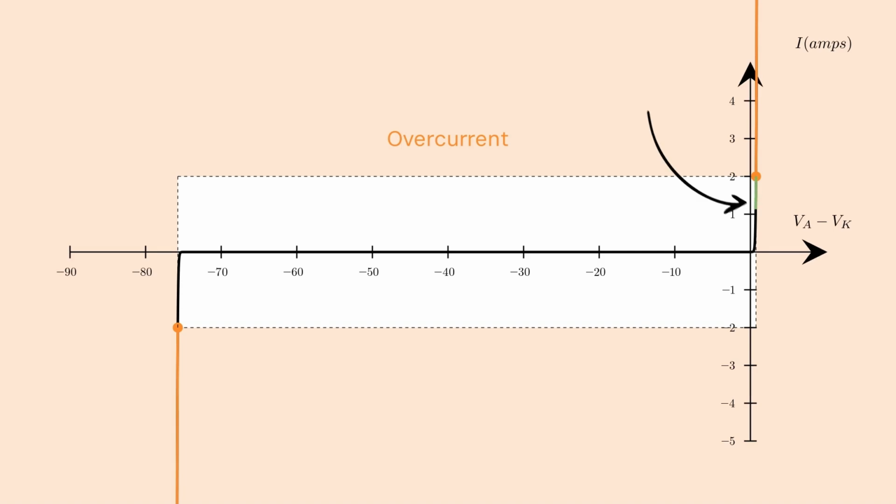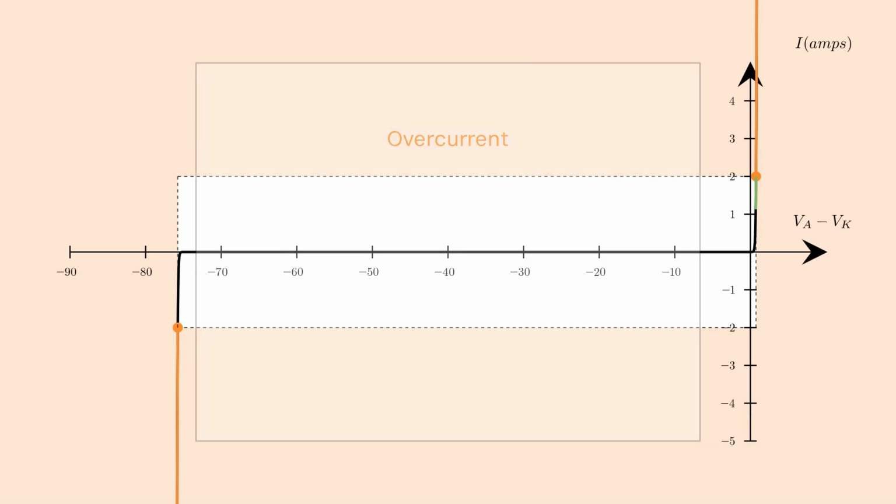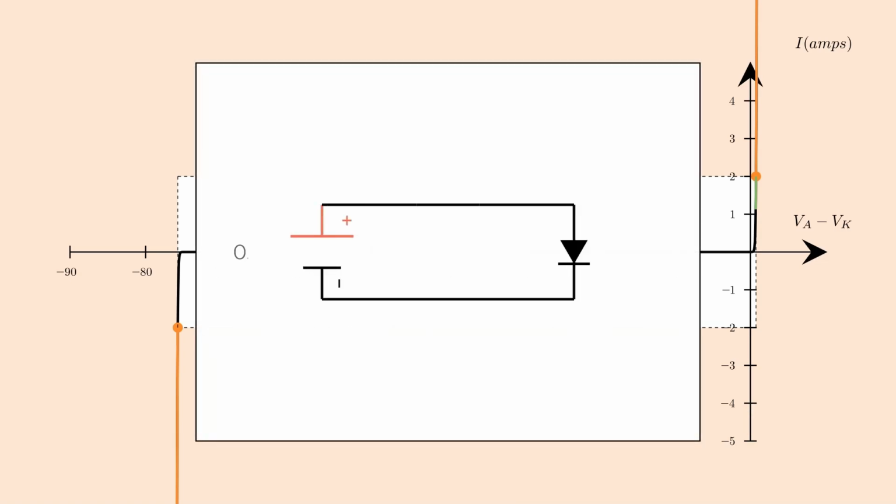In practice, the voltage range where you have forward bias is very narrow, usually a fraction of a volt, and it's pretty tricky to control the voltage directly to keep it there, mainly because the shape of this plot will change with the temperature of the diode, so a safe voltage range at 10 degrees may not be safe at 40. The usual solution is to limit the current rather than the voltage. You can do so using a resistor like this.